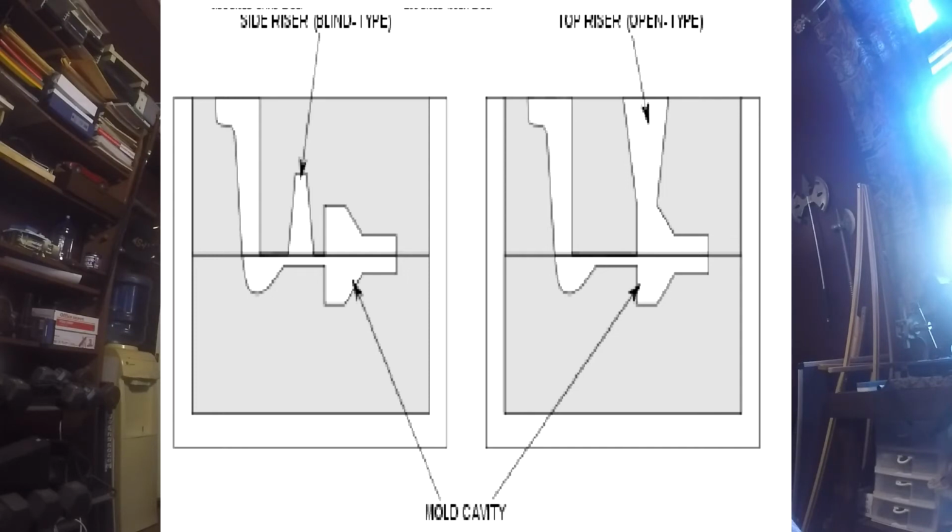And if you have it thick up there, you've got extra metal that will continue to feed that casting down below as it's solidifying.